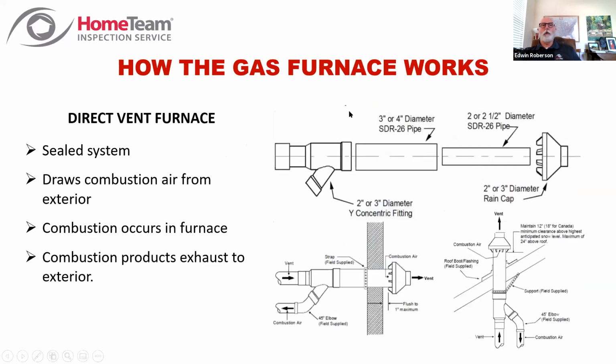Then in the more efficient, high efficiency furnaces, very often you're using what's called a direct vent furnace. And this would be a similar concept to your direct vent fireplace flue also, where you see this kind of hood sticking out the side, or sometimes it's sticking out the roof. You're actually looking at a pipe inside a pipe, so that if you look at this head, you draw the air incoming through the back of this head into one pipe, and it's concentric.